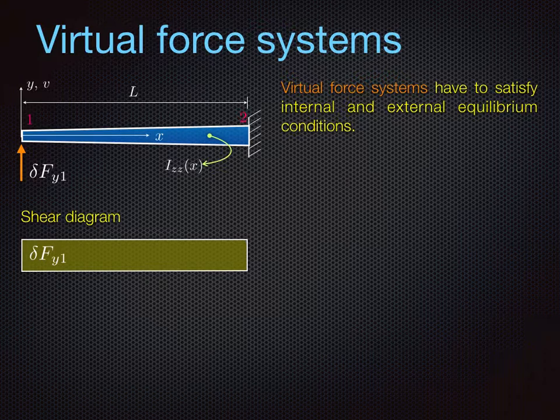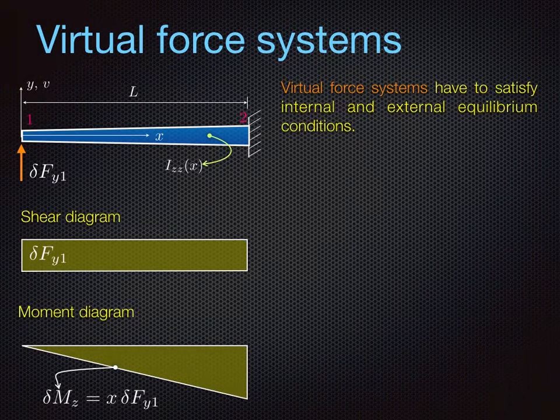And the corresponding moment diagram, which we will eventually, as you will see, use to compute the internal complementary virtual work, is a linear one. And this, the one that I'm showing you here, the moment diagram, is indeed compatible with the virtual force system that I have applied externally. Sometimes people make the mistake of using moment diagrams that are not consistent with the force diagrams or the shear diagrams, and then it would just produce an inconsistent system, and the principle of virtual forces will not work then.